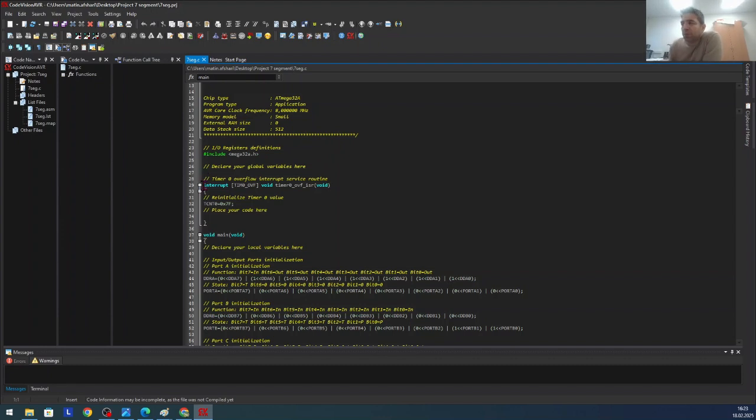We activated the interrupt, as you saw, and the 7F, you remember, it comes here basically. It says anytime that the interrupt is happening, every 4 milliseconds, you come and reset the counter value to this value, 130. This is 130 in decimal. So start counting from 130 to 255 instead of from 0.